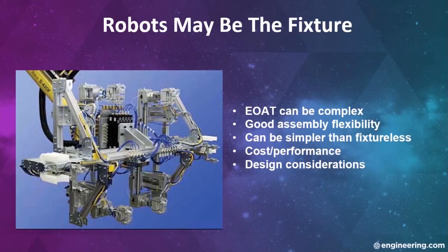Now, the ability to rotate a fixtured part or assembly through multiple axes can give similar benefits to that fully fixtureless solution I just talked about, with lower cost and complexity. Now, this kind of solution can also reduce or eliminate jigs by bringing the part or assembly to the punching, forming, or cutting operation rather than guiding a tool into the work. For volume production with larger assemblies, this strategy also opens up an interesting possibility, and that's the ability to pick up and hold multi-part assemblies for alignment or finishing work.